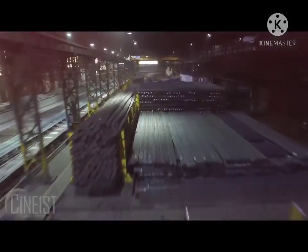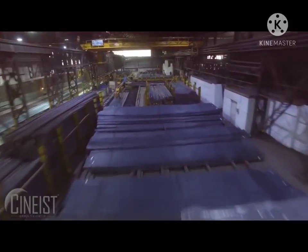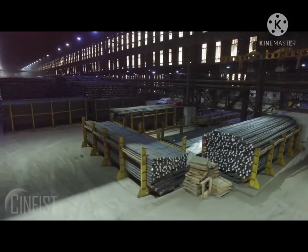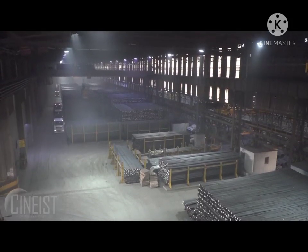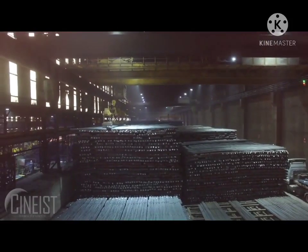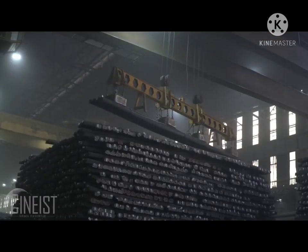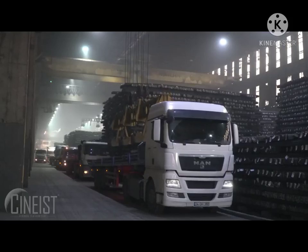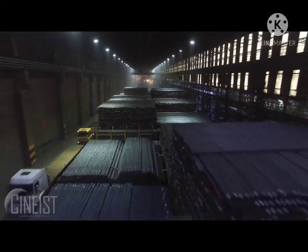Number two, electric arc furnace. In the electric arc furnace or EAF method, high-current electric arcs from electrodes melt large quantities of steel scrap into liquid. While the steel scrap metal is melting, the technicians add ferroalloys until the metal liquid reaches its desired ratio of steel to other alloys, such as chromium and nickel, which form stainless steel.